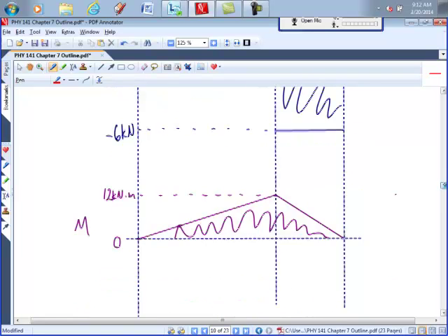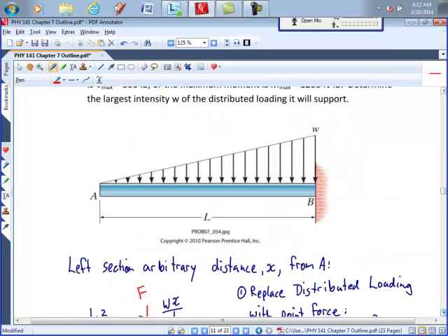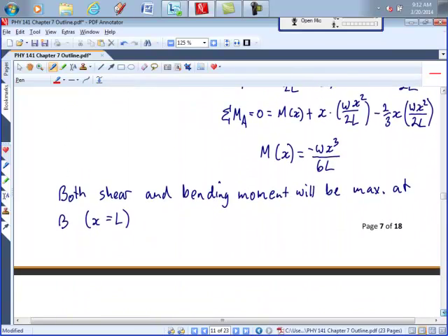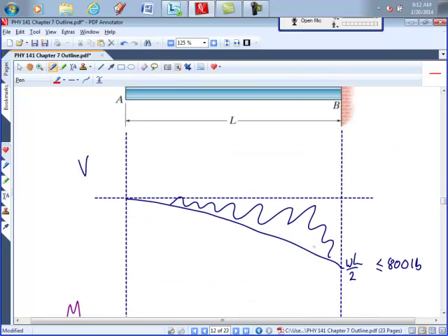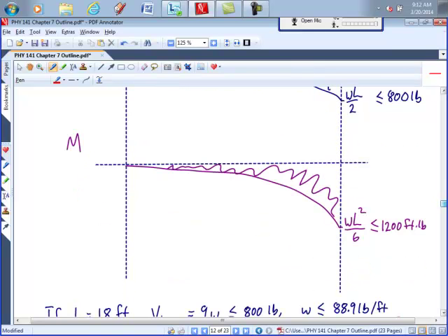And in the second case, which was a little more complicated, the shear diagram was a parabolic function, or a quadratic function, and then the bending moment was a cubic function. Based on that, can you make a guess at what the relationship might be between the shear diagram and the moment? The shear at any point is the derivative of the moment? That's exactly right.